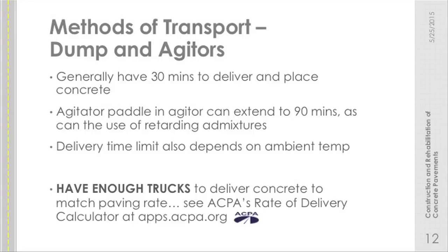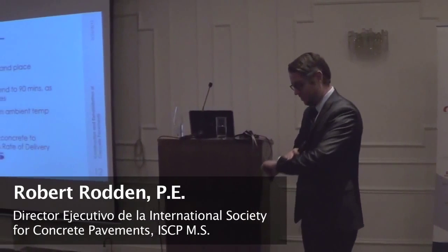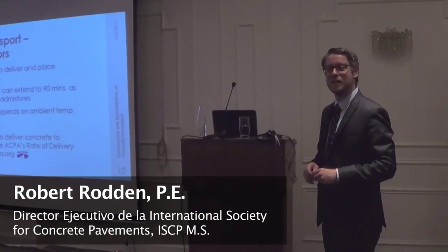Now, generally, you have about 30 minutes to deliver and place the concrete. That's a pretty small window, especially when we're talking about very large projects. And if they're at any distance from a city, or if it's like it was this morning at 8 a.m. in Santiago and there's traffic.